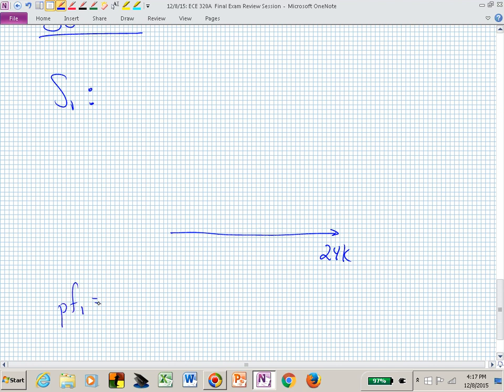We were given the power factor, weren't we? And the power factor is the cosine of theta sub 1. We were told that was 0.6, and I've set this up so that 0.6 is 6 over 10, or 3/5. Now I know my horizontal distance is 3 and my hypotenuse is 5. Now I have a 3, 4, 5 triangle if I'm using the trig, if I want to.